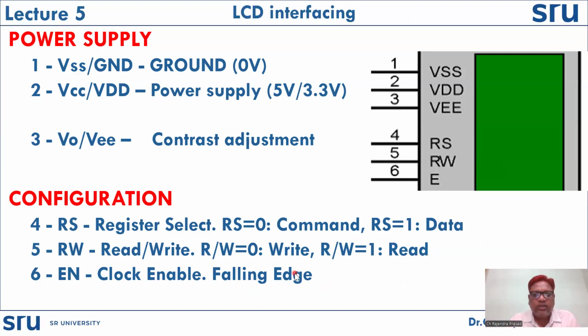And one more important thing, this enable signal saves the power consumption of the LCD by disabling the data bus. The LCD has an 8-bit data bus.